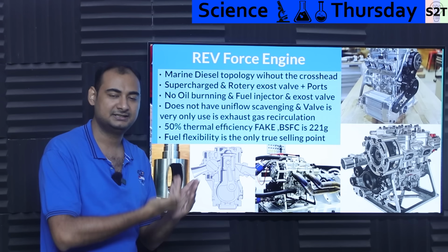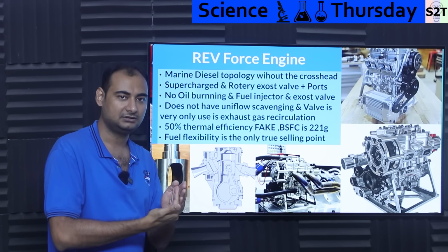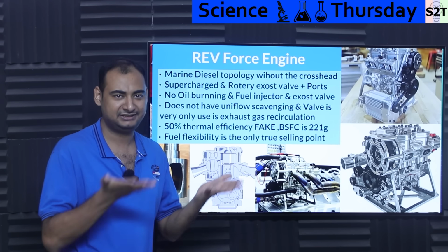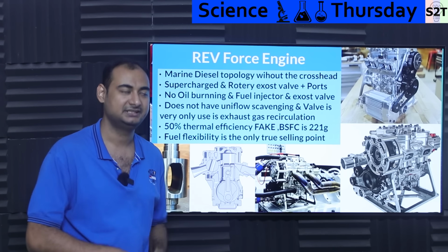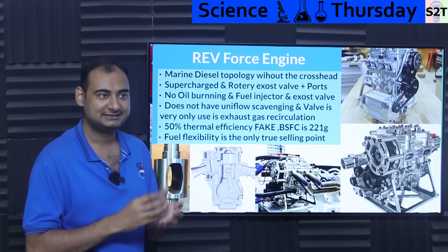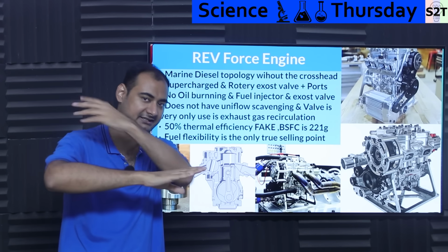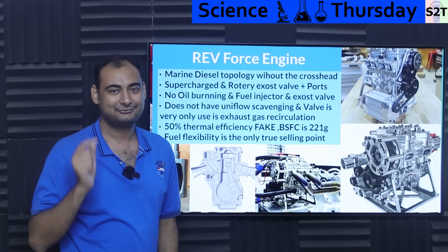And they don't have poppet valves in the intake. Poppet valves basically need a port injector simply because that allows them to clean. Now, why do you need to clean your intake valves? Exhaust valves get cleaned simply because there is hot exhaust, hot cleansing. The intake does not get that hot. The surface is hot, but the rod side is getting clean air. Now, the problem with that clean air is that generally you get oil from the crankcase.